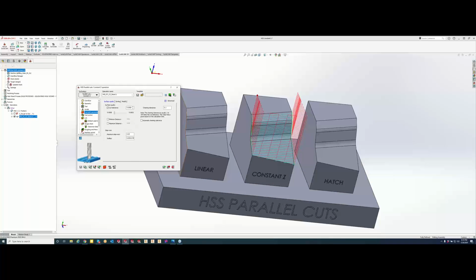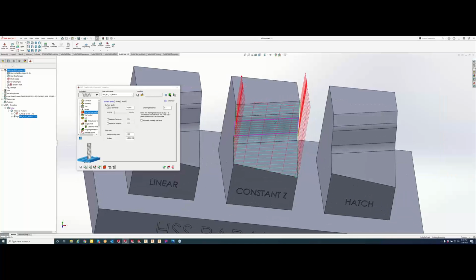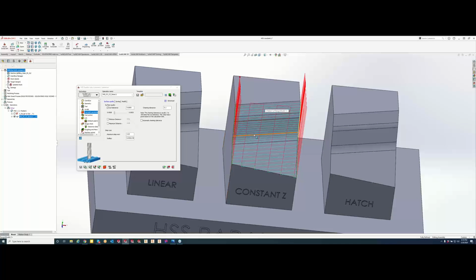So right here, we have a cut tolerance of 8/10. If we need to turn that down to a smaller tolerance, the only time I've run across that is if we're working in kind of a tight area, we can turn that down a little bit. And you guys can make that number whatever you like. But what I like to do here is keep your step over large. So right now, I can see all my tool path that is going on back and forth.